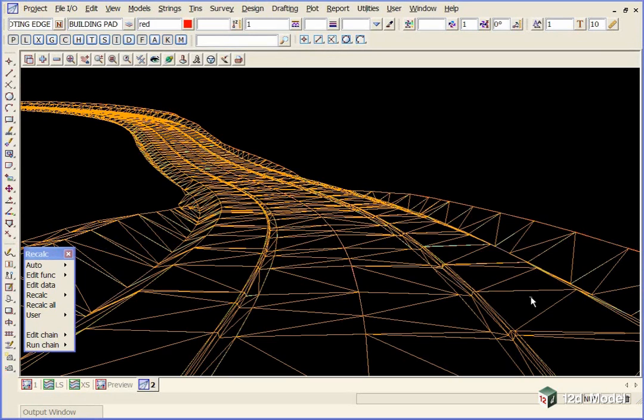We'll now take a look at more high quality plots rather than the quick plots that we've just produced, particularly when we're doing long section and cross section plots where you've got many pages of plots and you're required to have layouts including information such as labelling of chainages and heights, depths, alignment geometry and all the services, etc. Then we use what we call a PPF or a plot parameter file.